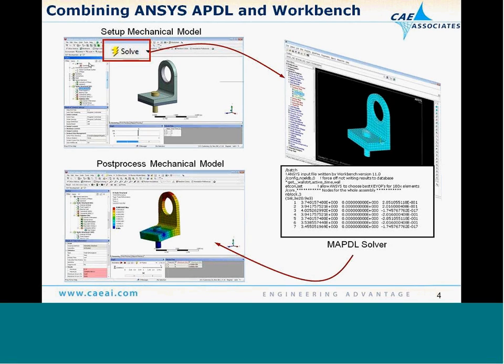So what you see in the Mechanical environment has to get written out to a corresponding ANSYS Classic command, which is your full model that shows up in Classic where it's solved. So this is really what we're going to be talking about today. How do we interact with this input file? How do we stuff our own commands into this to control different things?